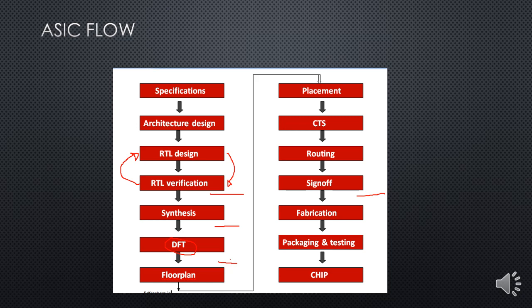Let's say we have a RAM which is able to store 1 MB of data. If our specification says that we need 4 MB, what we do is use 4 such RAMs. 1, 2, sorry, I'm bad at drawing here, 3 and 4.